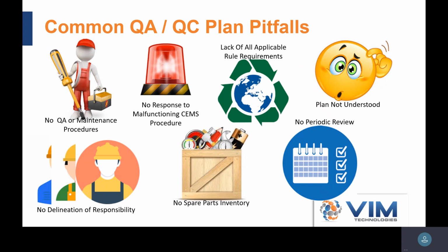QA/QC plan requirements. What I think should happen is to integrate those all together so you have one comprehensive document. Another pitfall is that the plan's not understood, where the plan is simply there to comply with the regulation and it's never been passed over the eyes of the people who actually do the work, usually the instrument techs or the instrumentation team. So they don't understand what's in it. Part of the time it's because there's no periodic review. I always recommend an annual review of your QA/QC plan. You can make improvements to it. You can make it an actual tool to help your program when people come and go, and it's a good